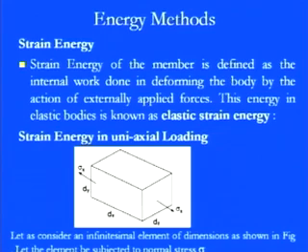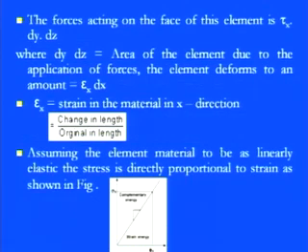So sigma x, and sigma x is going in this way, sigma y, sigma z, and all these small segments are there. If you are going for an infinitesimal element of dimensions dx, dy, dz, then our main focus is just to look at sigma x. You see here, the forces acting on the face of this element are tau x dy, because the stresses are just in that particular x axis form.